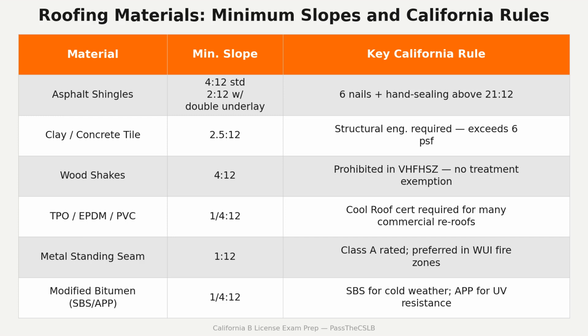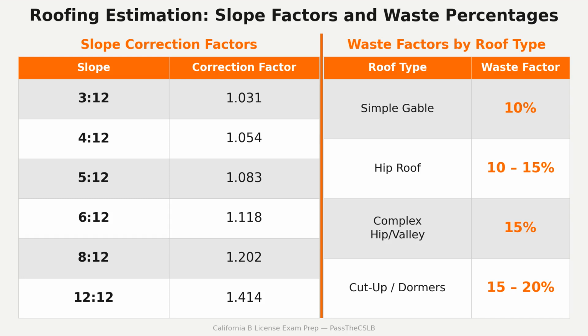Here is something worth holding about valley rafters. Every jack rafter on both sides of a valley dumps its load into the valley rafter. That member carries accumulated loads from both planes like a sloped floor girder. Size it wrong and the valley sags visibly over time. An experienced inspector can see a sagging valley from the ground and knows exactly what it means.